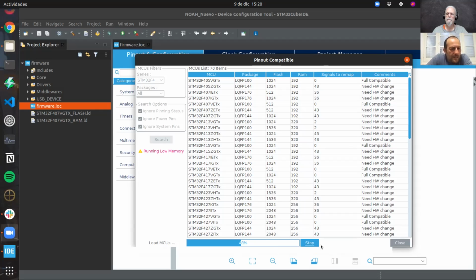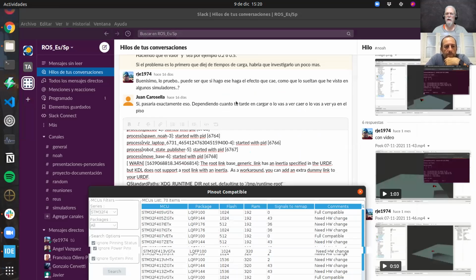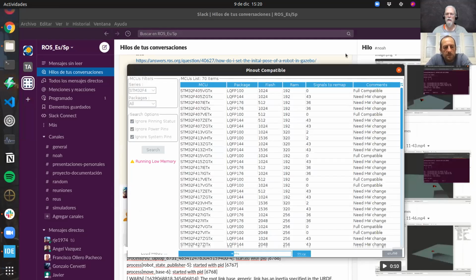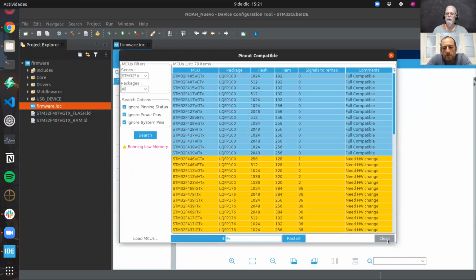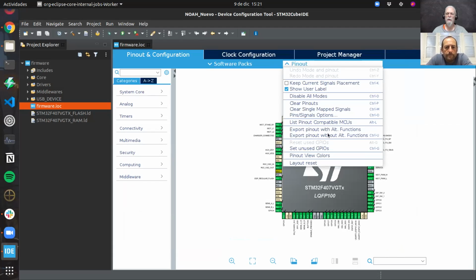Okay, if you wait a second, I will tell you. But I assume it's like a UART interface that they're running, and that avoids all the USB mess that you would have to do otherwise. Yes. So you just have to figure out on your new board which the UART pins are, and then hook it up to your Raspberry Pi. So yeah, that would be a very good thing to try right up front.